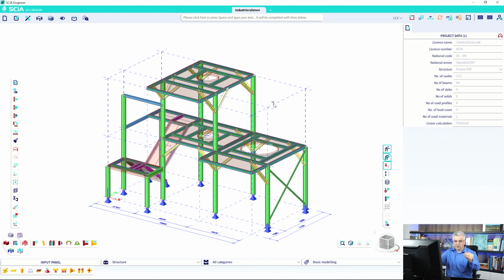Checkbot can read data from external programs, from analysis software, from CAD software, and also from a SAF file. The SAF file was developed by SCIA some years ago. It's an Excel file where you can store your full structure with the geometry, connections, loads, and also the results. The description is on the internet, and some companies that produce analysis software use this SAF file, so you can export it and then read it in Idea Statica Checkbot.